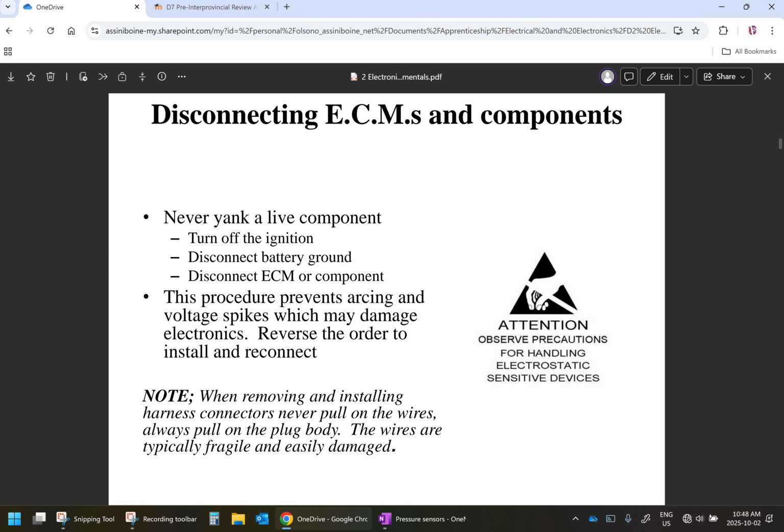And if you remember when I was talking about sensor diagnosis, I was telling you guys to purposely short and unplug stuff while it's powered up to try and create fault codes the opposite direction of what the issue was originally. Okay, so there is quite a difference between disconnecting and shorting out a 5 volt 10 milliamp circuit than disconnecting a current carrying 12 volt circuit that could create a spark. You create a spark, that's high voltage, that's how you damage electronics, right?